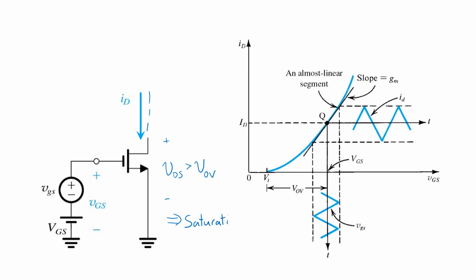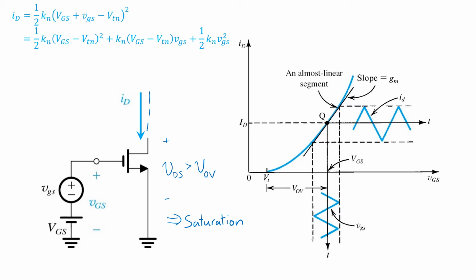Subject to this assumption, we know that the transistor's drain current obeys the square law. And that's written here. We've used the simple square law here, neglecting the term for channel length modulation, just to keep things simple for now. And we've written VGS in terms of its DC operating point part, and the superimposed small signal lowercase vgs. Now if we expand out the squared term here, we end up with this longer expression.